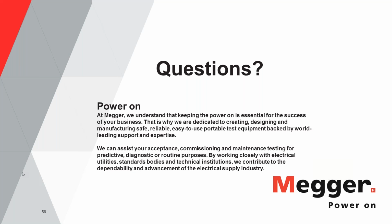All right. Next question is, what equipment is recommended to make the primary injection? I'm not quite sure if I understood your question, but as I said earlier, you need a high current source to run a primary injection test, and the type of test set, the size of the test set that you get will depend on the size of the breakers that you will need to test.